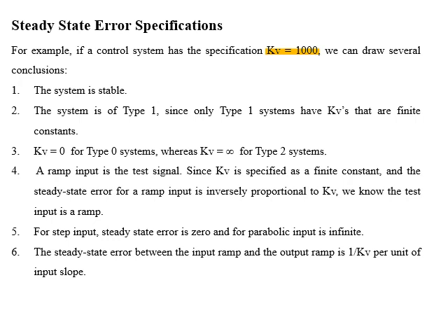Like, if steady-state error exists for stable systems only, then static error constants also exist for stable systems. So if velocity constant is given and its value is 1000, it means that our control system is a stable system.